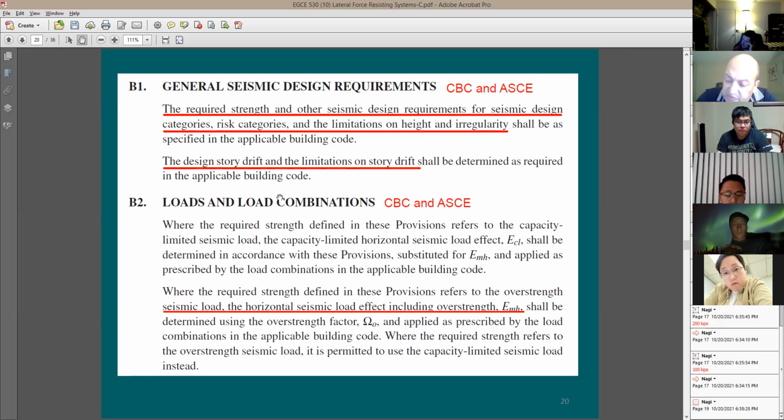Now we are going to have seismic forces that you need to include. And in many cases, you're going to see here a combination of seismic force and dead load. And then in some other cases, you're going to see here the terms EH and EV. EH means horizontal seismic force, and EV is the vertical seismic force.